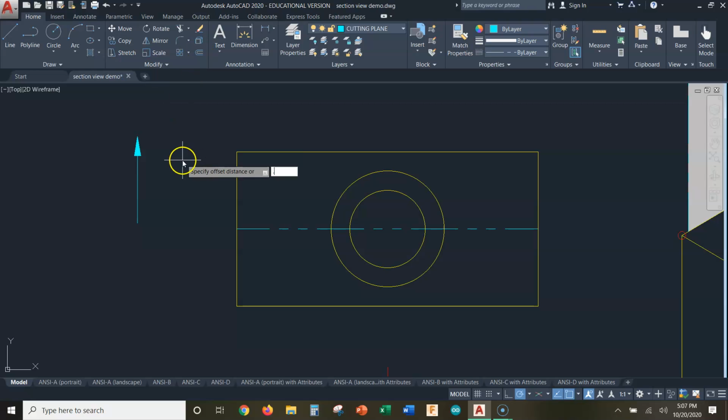I'm going to type in 0.5 and hit enter. I'm going to offset this line out here, and I'm going to offset this one up like that. Whoops. It lay right on there, so I'm just going to erase that because it's up there. And it's basically right at that point. So that's where my arrow tip needs to go. All I did was make some construction lines there, so I know where that is.